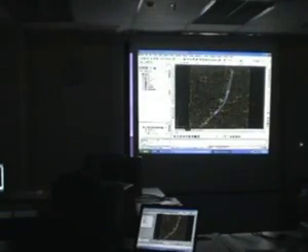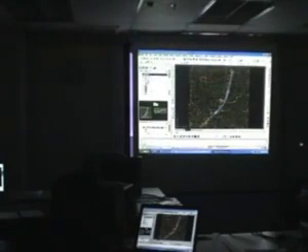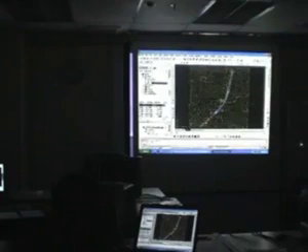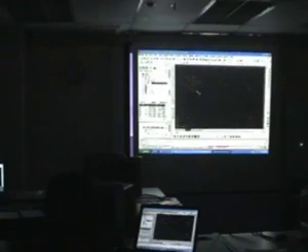On the Prospector, which basically contains the data that exists inside this drawing, like points. Okay, we've got all the points. If I click on the points list, you can see all the point information here. The advantage is that it's a lot easier to modify. Like in Land Desktop just now, remember I wanted to edit a point description. Let's say in this case we've got point 1248.